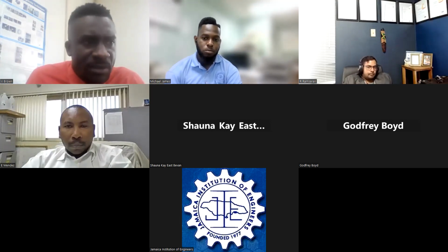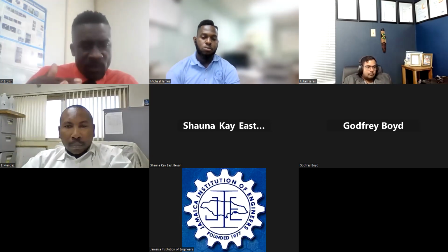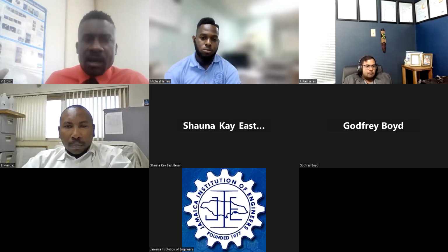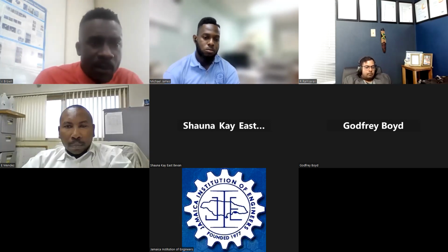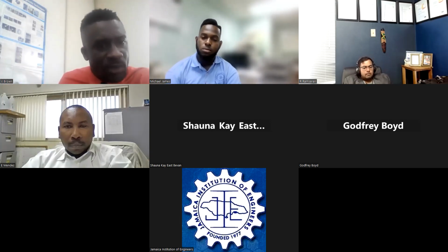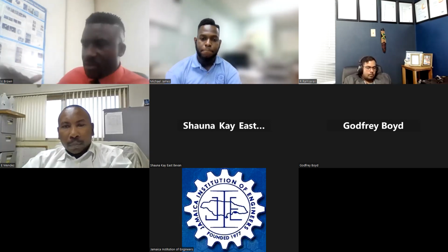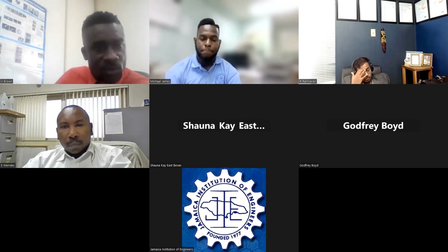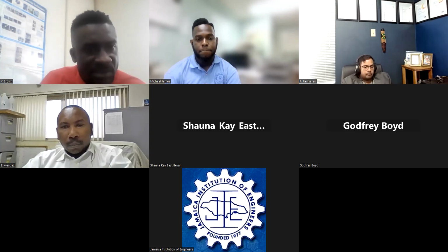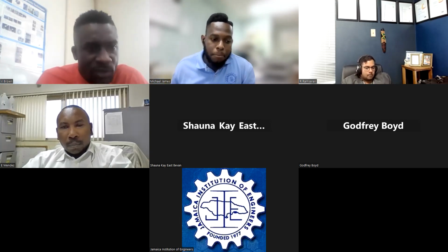Acceptance criteria comes in. You have your figures from whatever standard you're using, or whatever requirement you have for that motor based on the manufacturer's data sheet, or the sheet you get with that motor, the nameplate. So you test and compare to the nameplate values and also the data sheet. That's what you call the acceptance criteria, and you trend along that line.